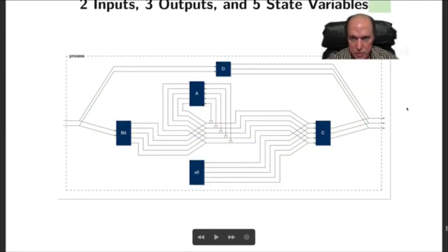So time 0 is very different from everything else. It's C times x0 plus D times U. And then after that, you're looking at the input through B, and the output is C times the feedback. I'm about to say the transfer function, but I guess I could say C times (zI minus A) inverse times B, but that's not fair because I haven't derived that for you. But you can see right here what it's doing.